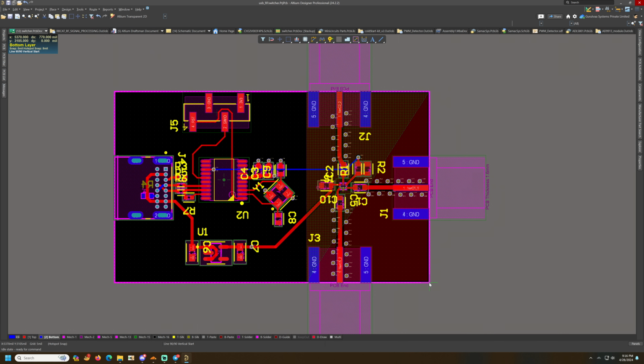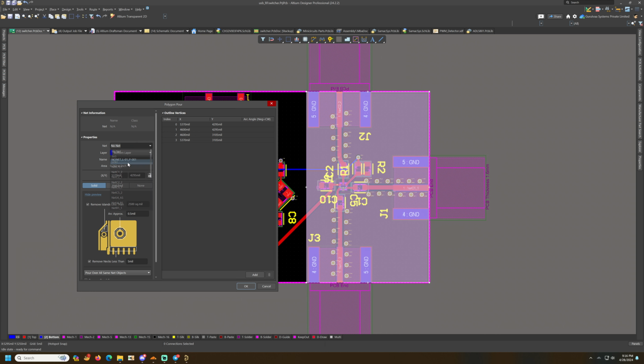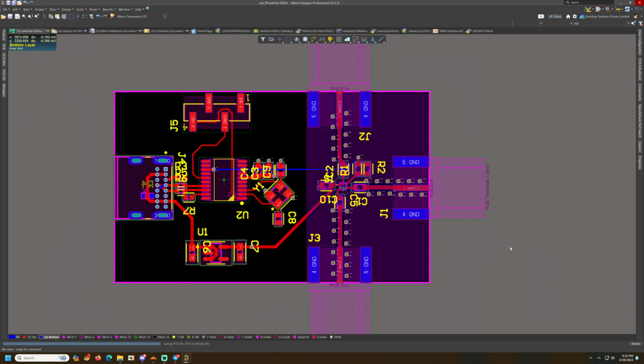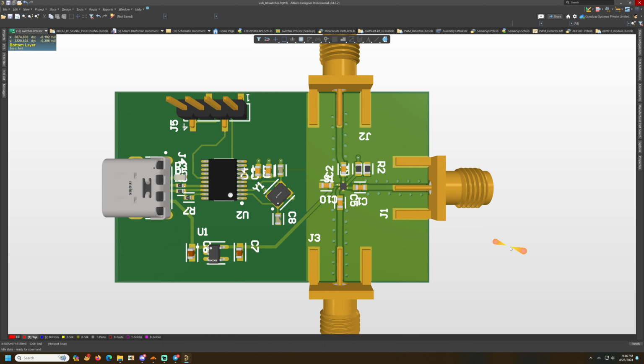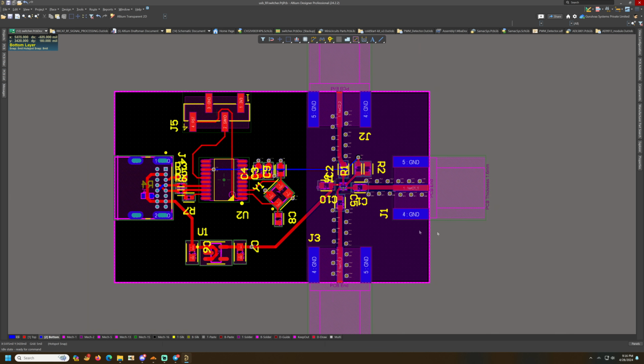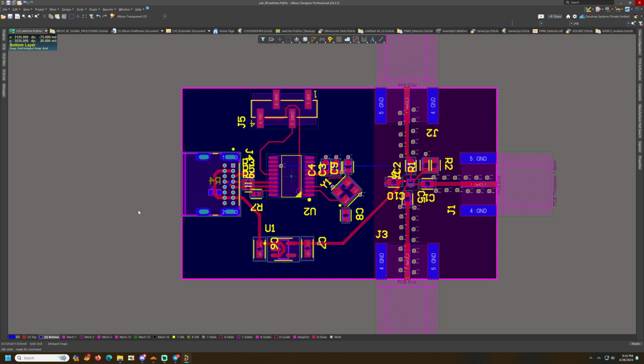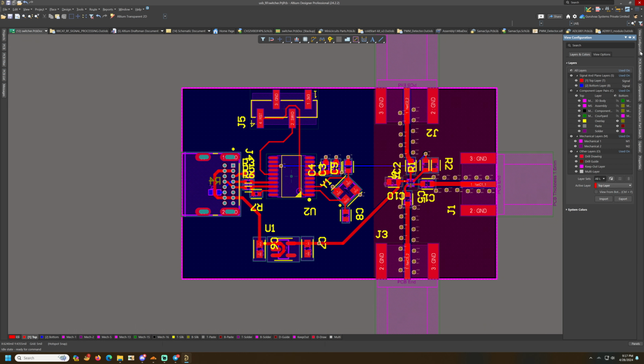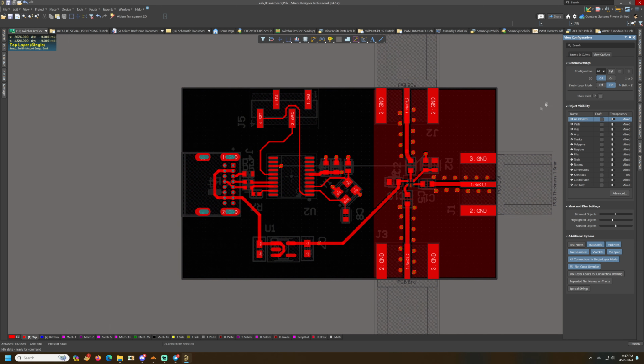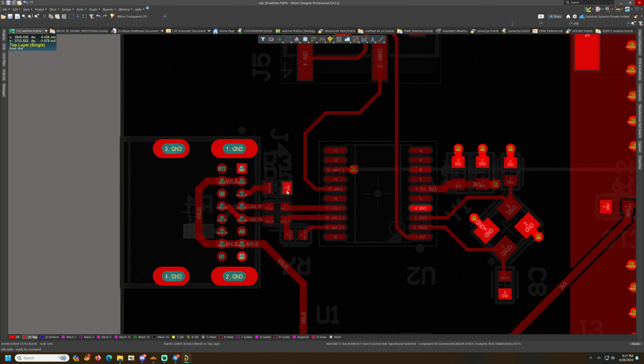But the wavelength that we are talking about is in free space. The wavelength on the PCB on an FR4 substrate becomes even smaller, so the smaller spacing between the vias on the shielding makes sense. It should be as small as possible in order to prevent any leakage and to maintain the 50 ohms impedance that we intend to have.